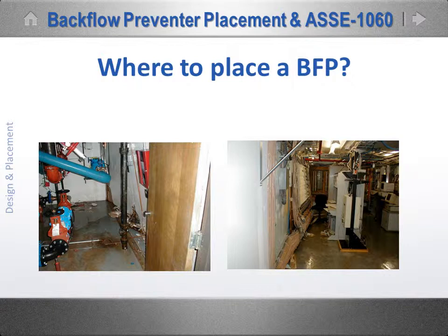This flood occurred in a Nashville hospital mechanical room and caused over $1 million in damage. What you're looking at is 2 sides of one wall. On the left, you see that the sudden water volume discharged from that Wilkins RPZ there with a floor drain right next to it moved the wall probably 18 inches into the next room, which happened to be a telephone and low voltage wiring room.